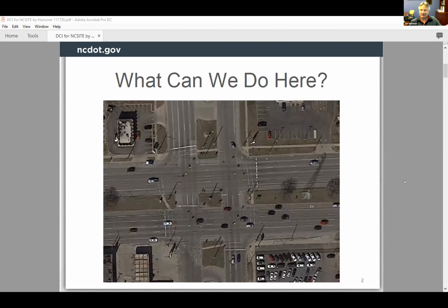And what I've got in mind is what can we do about places like this? This is not in North Carolina, but we do have some intersections like this in North Carolina. This is an 8-lane arterial meets a 6-lane arterial. Currently it has a median U-turn design, but in the peak hours, at least non-COVID peak hours, this thing is badly over capacity. As you probably know, a median U-turn delivers decent capacity, better than conventional. Of course, anything beats conventional.